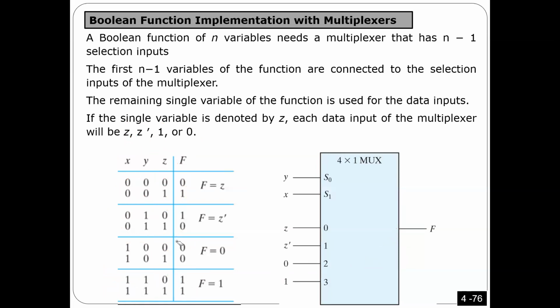Yes, you can. So I can use this one here for the selector. But now, when the input is 0, 0 here, it will be this case and another case, this case. Because this is 0, 0, 0, 0, these 2 cases are going to connect input 0 to the output.